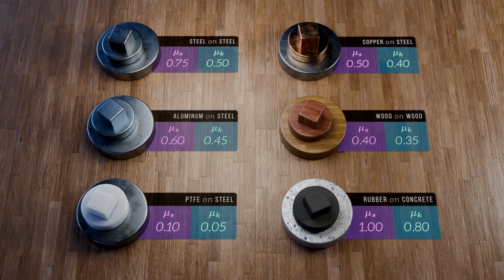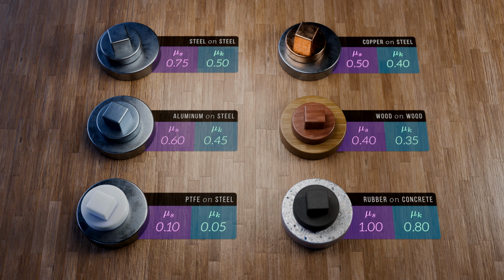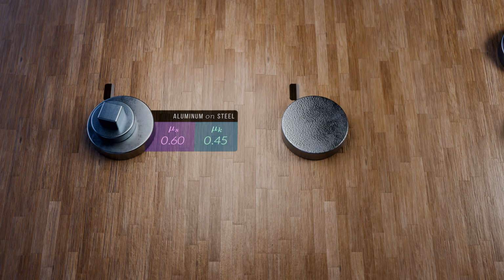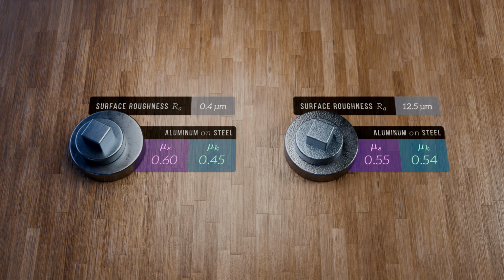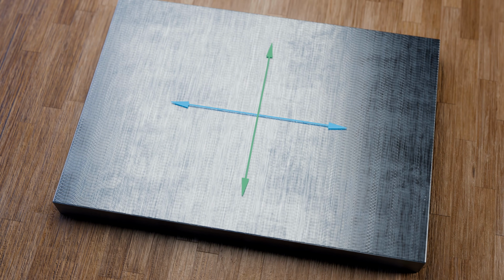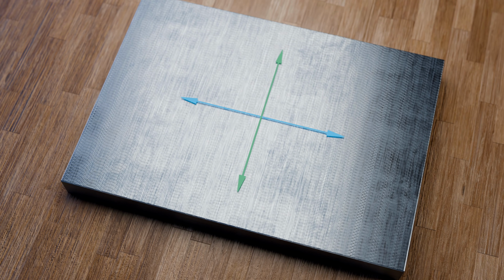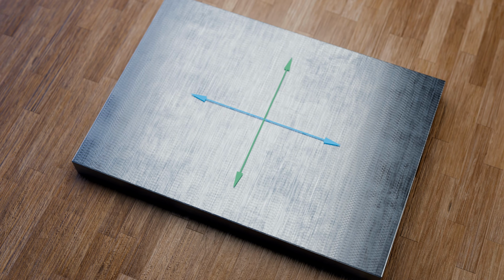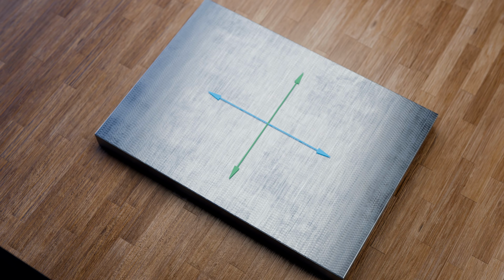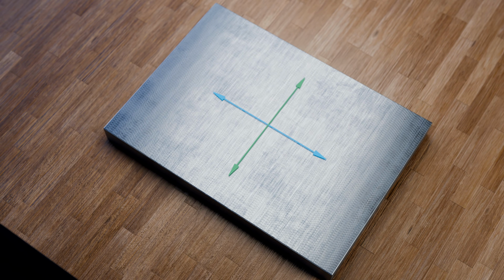The difficulty with the coefficient of friction is that it depends on much more than just the materials involved, so these are all very approximate values. Surface roughness has a big impact because it affects the likelihood of mechanical interlocking at asperities. Even machined surfaces, with their directional textures, can have different friction coefficients in different directions. Then there's the presence of surface oxide layers, cleanliness, temperature, and even heat treatment that can all have an impact on friction. Because of all of these different factors at play, the coefficient of friction is an empirical parameter. It can only really be determined experimentally.